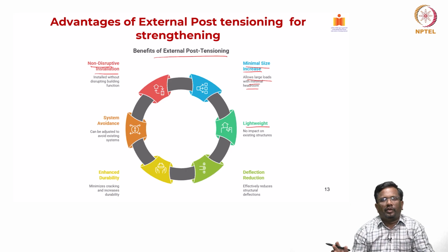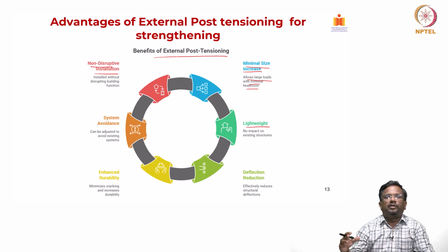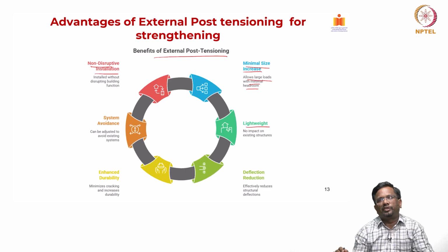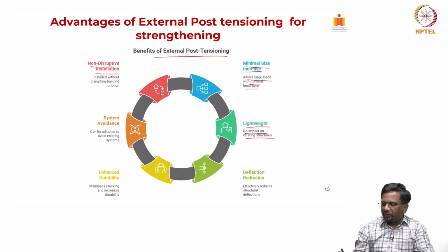If you are doing concrete enlargement along with the external PT, then you are adding some weight, but otherwise the weight of the cable itself is not going to significantly change the weight of the structure. So, no impact on existing structures, and as we have seen, deflection reduction.